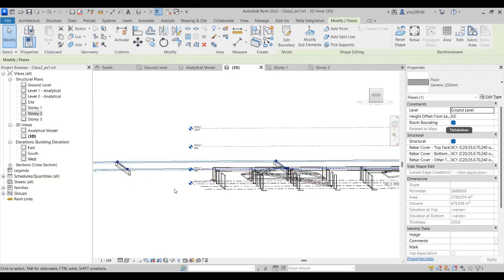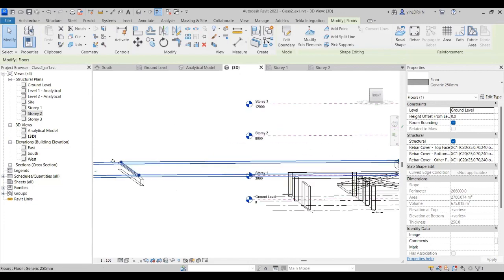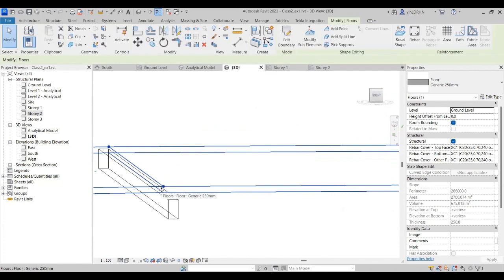So when you do the steel beam with the bond slab or other type of slab, this tool is useful. You can raise up this one, but again, I advise you don't use this kind of tool if you want to use it for analytical purpose because the reason is very simple. Center lines are not properly aligned. These tools are good for easy modeling, but it's not good for analytical purpose, right? Sometimes unfortunately we may need to use it because we have to do the model the real way, right? But structurally sometimes we may need to simplify it, right, for our analytical purpose.